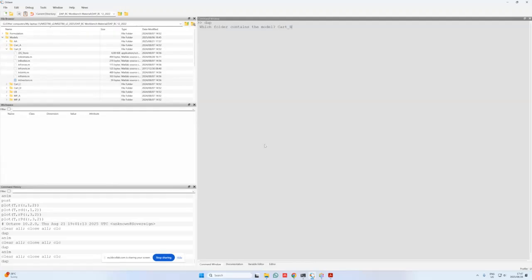Now our model that we're considering is card_B. Do I want to create the initial conditions? Yes. And in this case, after initial condition correction, I can see that all of my initial velocities are 0, and this is in line with the new specification that I have on the angular velocity. It starts at 0, and it then decreases to minus 2 pi radians per second. So that is fine that I have an initial velocity of 0 for all of the bodies.